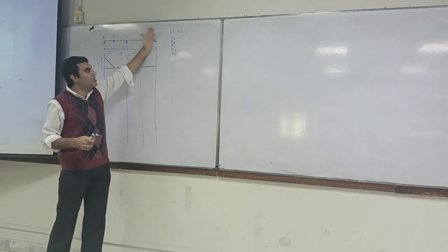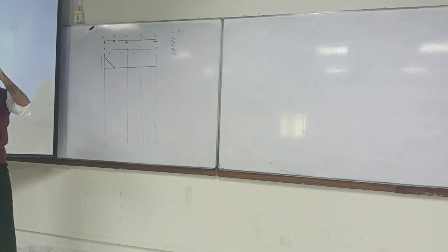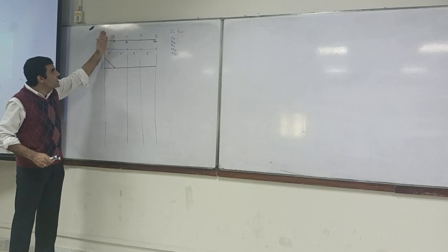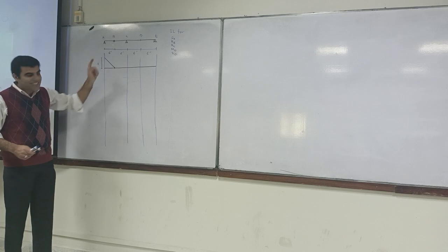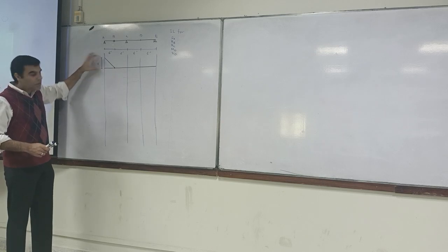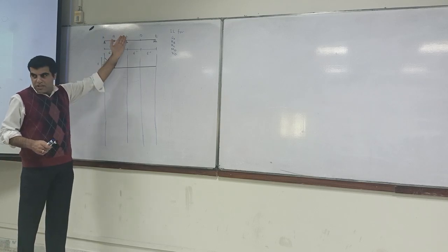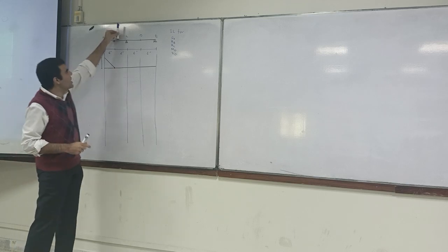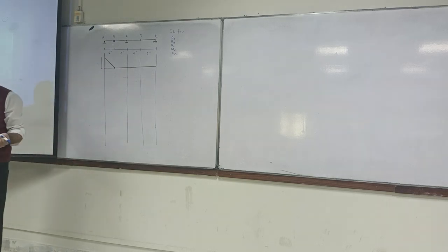Keep on moving it until you reach E, and you will keep on finding the value. Now let us do a sense check on this, whether this makes sense or not. If we have a unit load in this area, between A and B, it's only then that RA would be active. As it moves to the other side, this will be inactive. If it is over here, then this is just like a link, and this is not going to take any load.